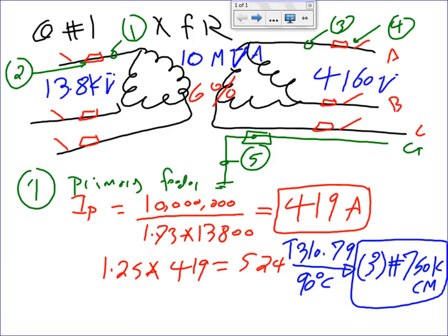Any question, guys? Straightforward. We're assuming it's a multi-conductor cable here. Is this outside? Underground ducts. What do you mean? Do we have to derate for the temperature of the conductor? It's underground temperature. Look at the table. It's based on the ground temperature.